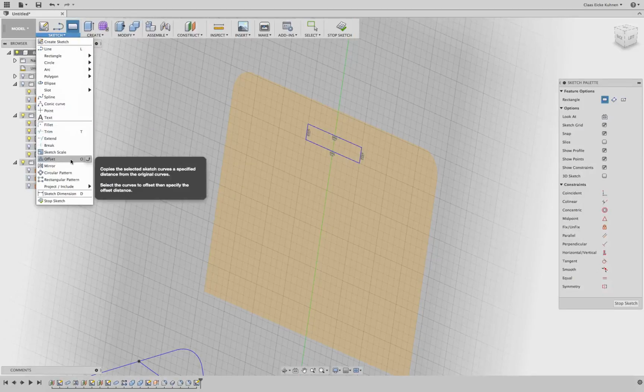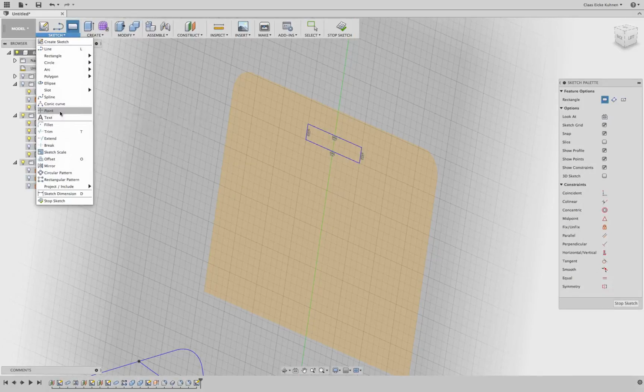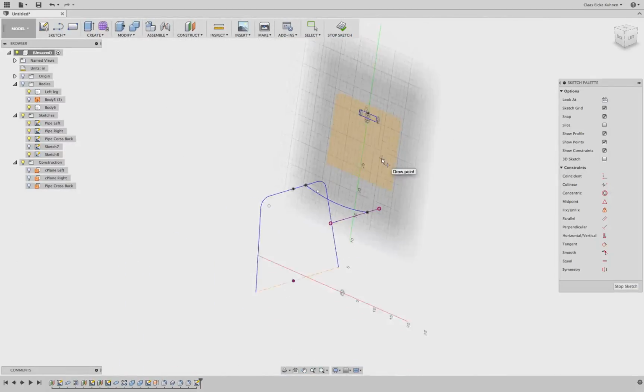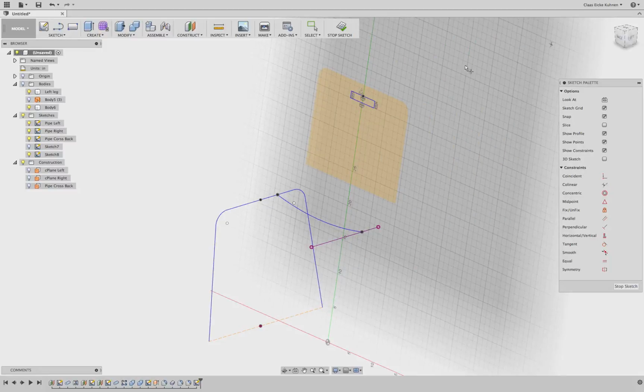Again, there, for example, we can add a point, let's say here on this mid part. Now, because my whole object got first created centered nicely onto the world, now this point I can select vertical constraint to my sketch center.